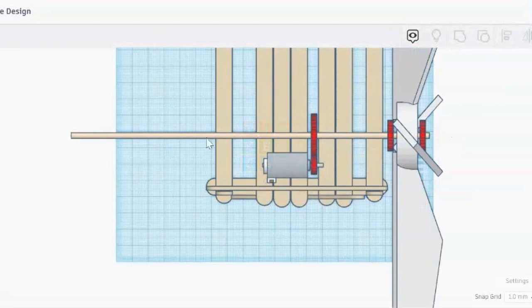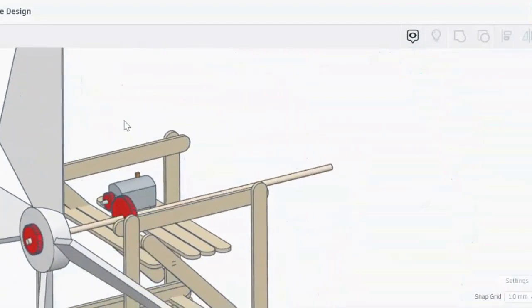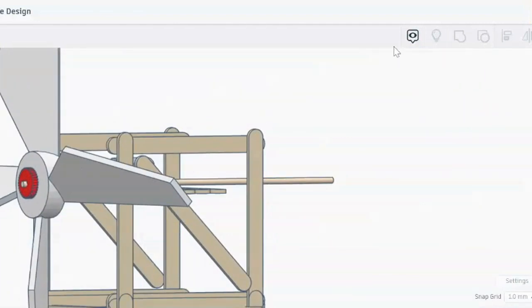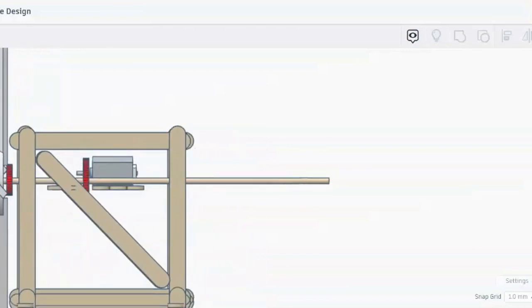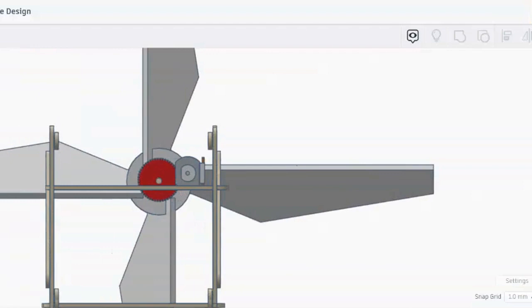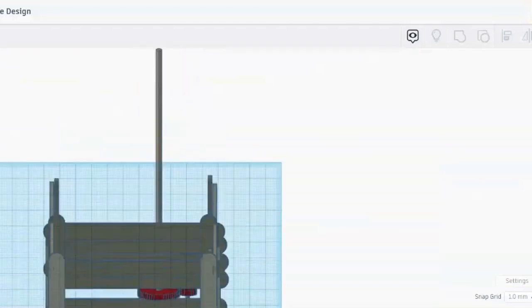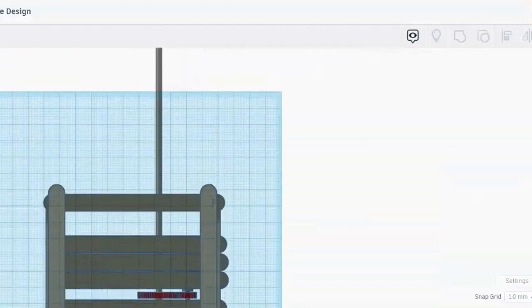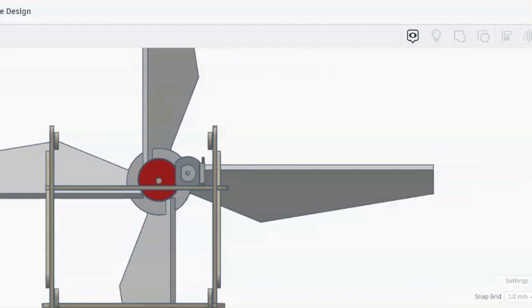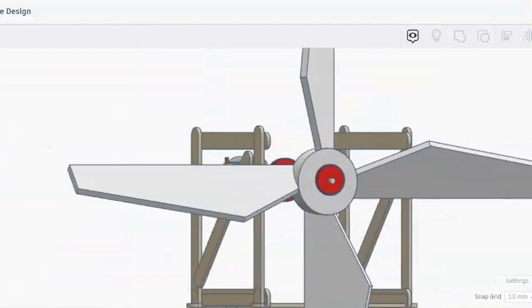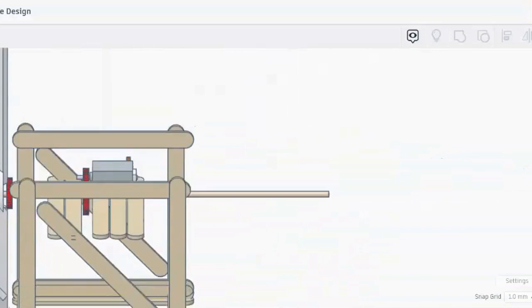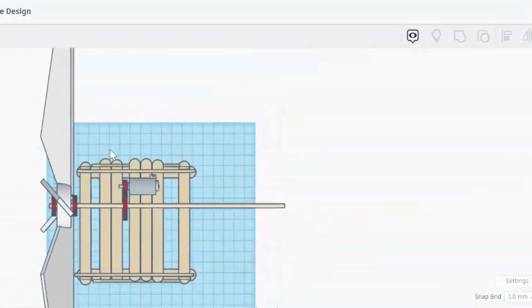And I'm just going to walk you around a bit to give you a sense of how this was put together. Again, we have our different views, which really matter, right? So right now, I'm in orthographic view. So if I choose any of the directions that are in the center of the cube, in other words, top, bottom, back, left, right, front, I'm going to get a head-on view.